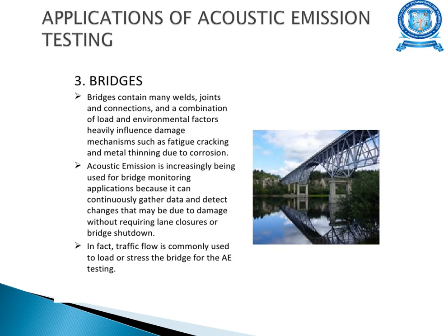So all these defects can be tested using acoustic emission. For monitoring of a bridge, you can use this test to find any damages or defects without requiring bridge shutdown. And traffic flow is commonly used to load or stress the bridge for the acoustic emission testing.